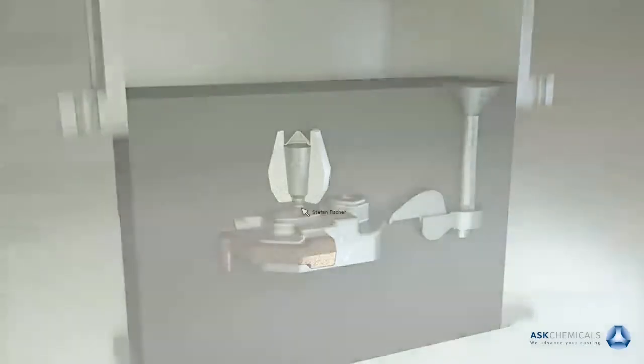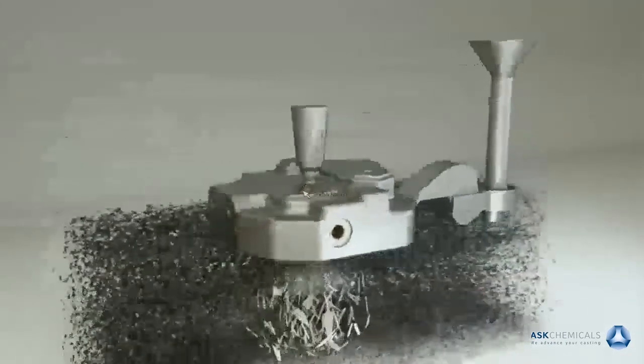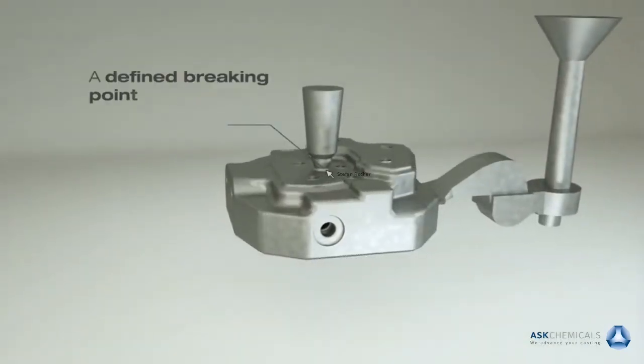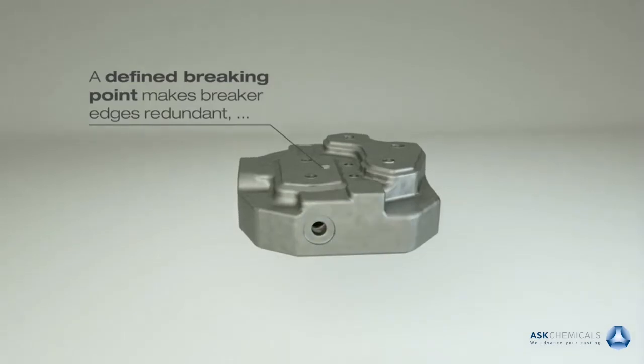Now you see the behavior during demolding, and you will see in a few seconds that with this reduced neck area, it's much easier to fettle the casting, meaning to knock off the residual riser rests, as you can see here with this very small section that we can achieve with this system.